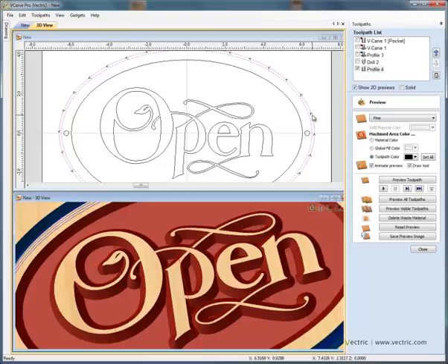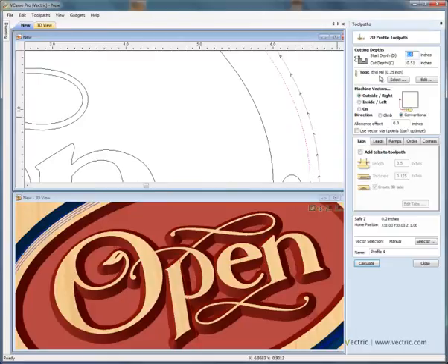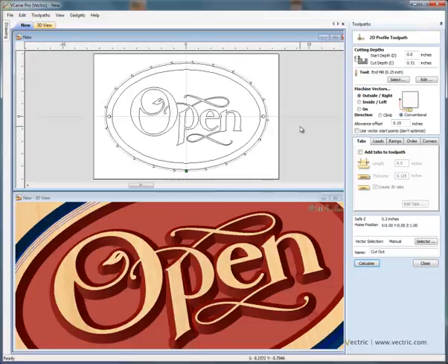You'll see here in the 2-dimensional view, the toolpath has been offset around the outermost edge by the radius of the cutter. If I double click to edit this toolpath, let's give this a different name, just to make it clearer. So we'll say cut out. But I don't want it cutting right up to the edge because we have a chamfer here. So I'm going to say I want an allowance on there of say 150 thousandths, so it will cut further away. Plus, we say F to zoom to fit.